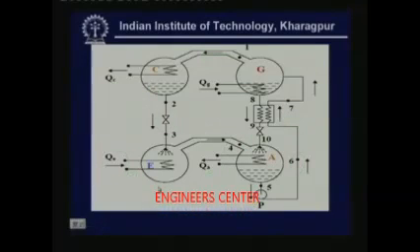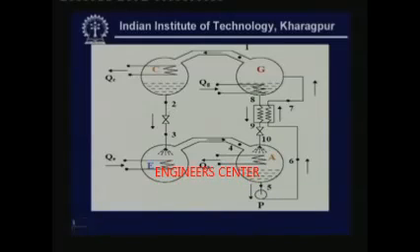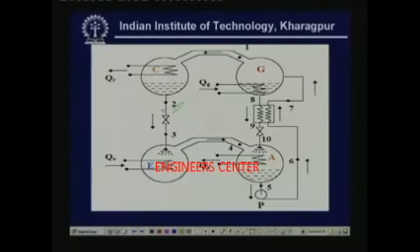So, again look at the points. Point 1 is the exit of the generator, pure refrigerant vapor at high pressure and high temperature. Point 2 is saturated refrigerant liquid at high pressure, at the exit of the condenser. Point 3 is a low pressure refrigerant at evaporator pressure, and point 4 is low temperature low pressure saturated vapor.